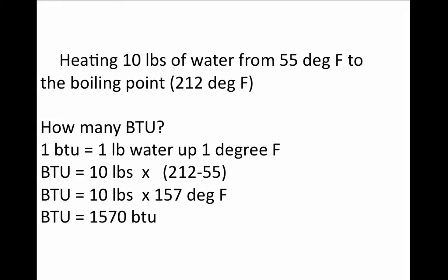So if we heat 10 pounds of water from 55 degrees Fahrenheit to the boiling point, 212, how many BTUs are involved? Well, let's first take a look at the definition of a BTU. A BTU means 1 pound of water up 1 degree Fahrenheit. So I want to know the total amount of BTUs involved in some kind of energy transformation. I need to know the pounds of water, and I need to know the degrees Fahrenheit.